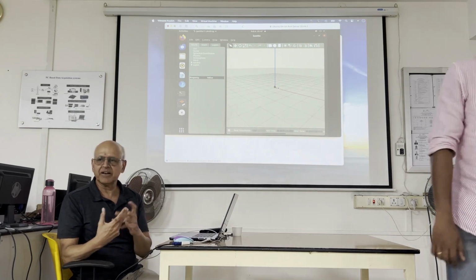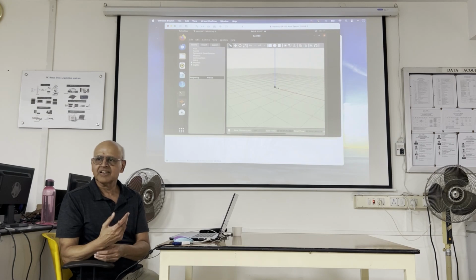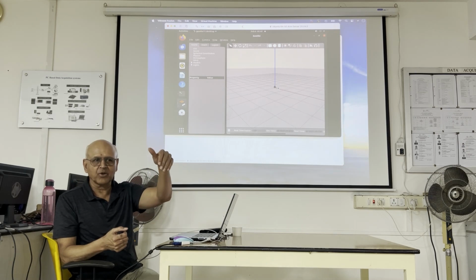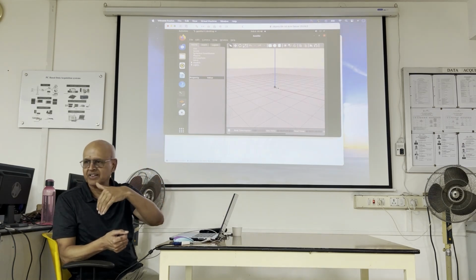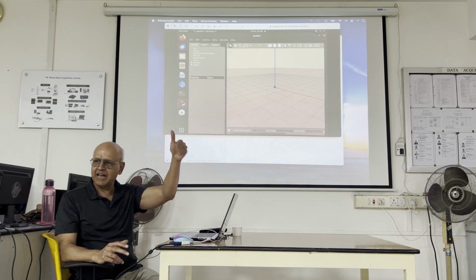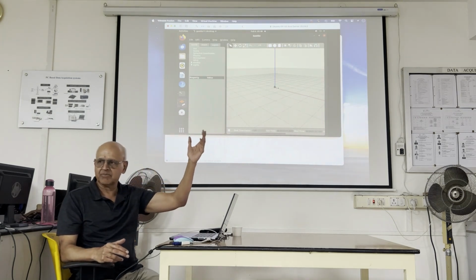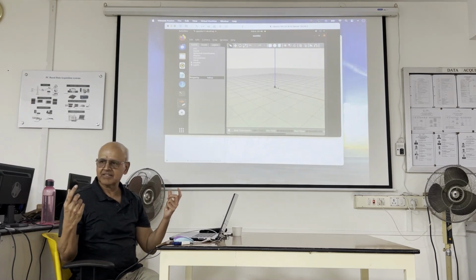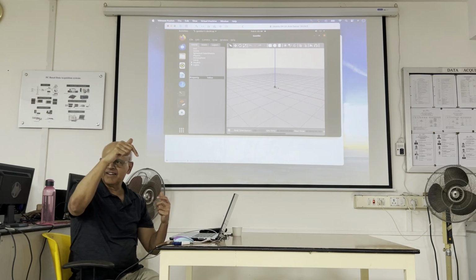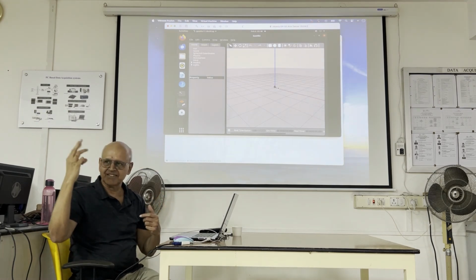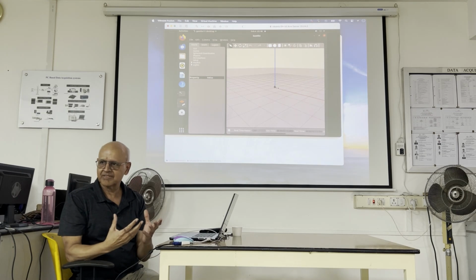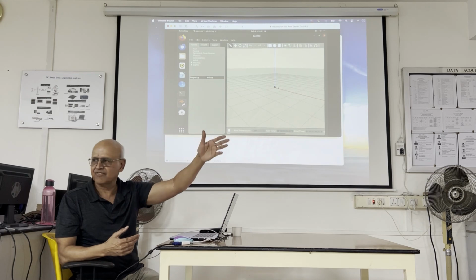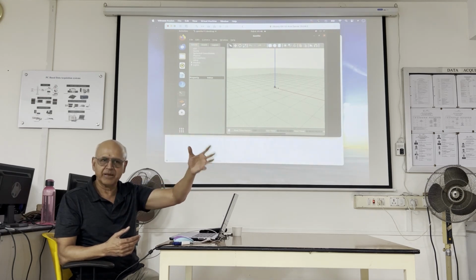It's because you could have multiple cameras on the robot. Maybe the cameras are fixed, but cameras fixed only means that their coordinate axis is fixed with respect to the robot frame. But the robot itself is moving, so the camera axis will be moving with respect to the world frame. Do you get that? Also, each of the 2 wheels has an axis. The LiDAR, wherever you mount the LiDAR, that has a 3-axis system. So, you might mount a camera on the wall of your lab. That camera has to have its own frame of reference called an axis.